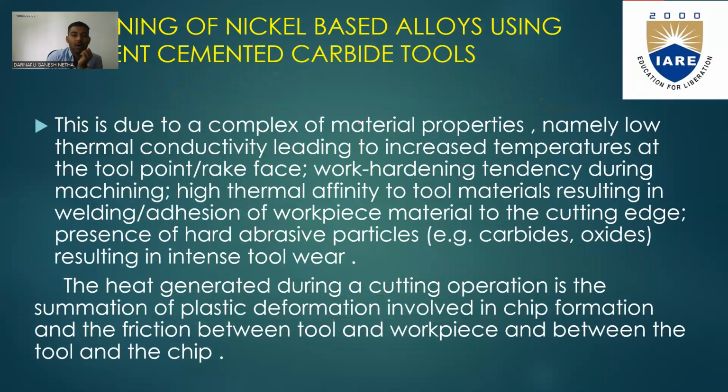This is due to a complex of material properties, namely low thermal conductivity leading to increased temperature at the tool point, the work hardening tendency during machining, and high thermal effect on the material resulting in welding adhesion of workpiece material to the cutting edge, and the presence of hard abrasive particles, for example carbides and oxides, resulting in tool wear.